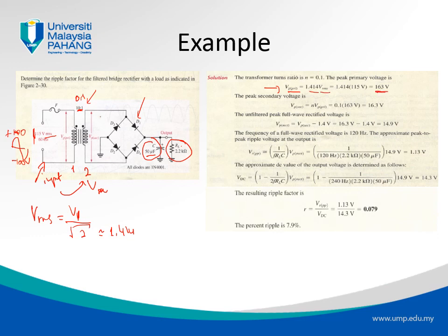So basically, our voltage in input is a 163 volts sinusoidal, 163 volts being the peak voltage. Once we know that, then in V secondary, Vp, the V peak of the secondary, equals the ratio multiplied by the V peak of the primary. We have a ratio of 10:1, 0.1. So now we have reduced the voltage by tenfold, and we have a peak voltage of 16.3 volts.